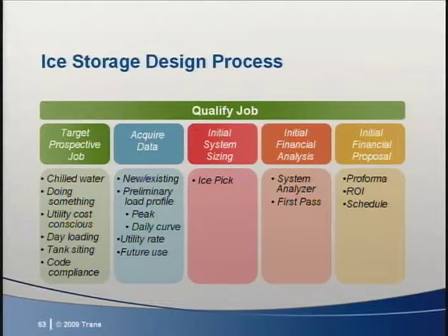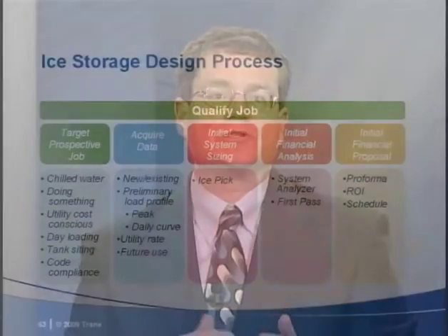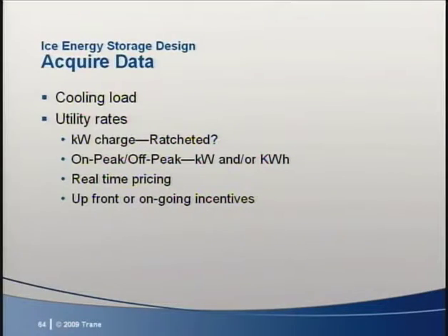As you well know, Paul, the available utility rates and modeling them properly is also critical to the qualification of any storage system. Particularly important is breaking out the demand charges and time of day or stepped rate structures. Modeling with a blended rate is a sure way to badly underestimate a storage system's savings potential. Electrical rates can be very complex today because of demand and cost pressures. But electrical rates are also complicated because setting rates is a political process. So rates come in many different shapes and sizes.